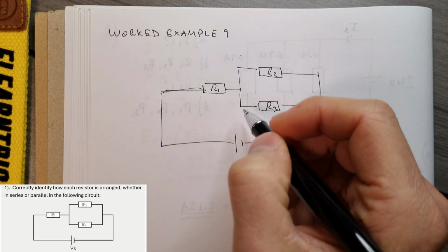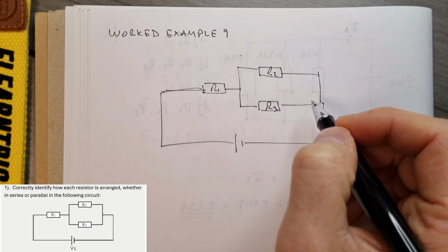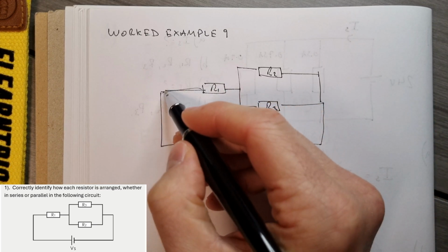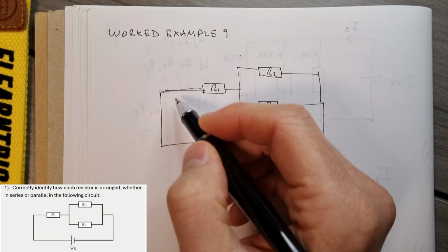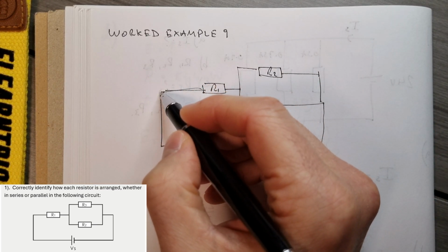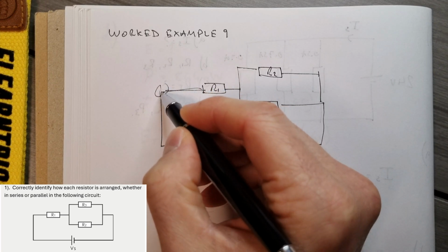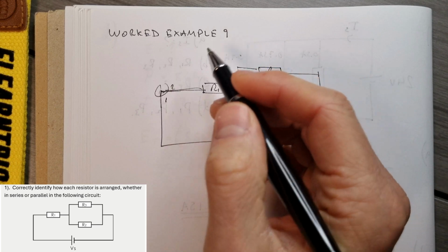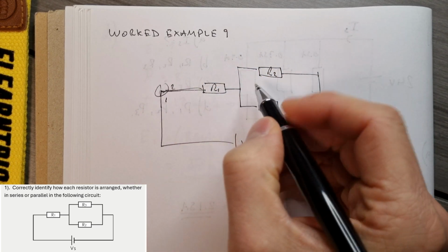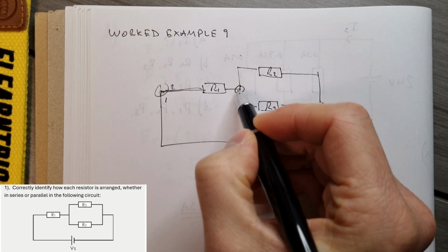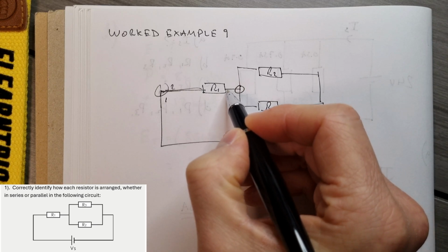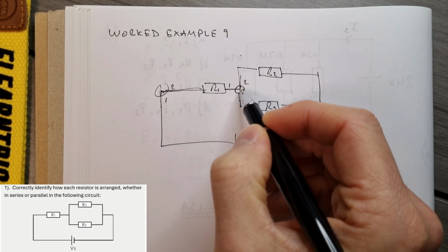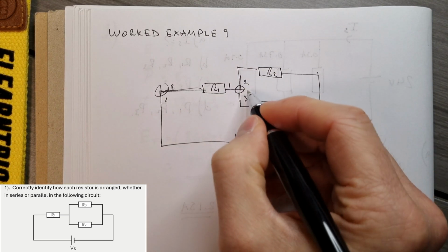First of all, identify all the parts in the circuit where there are effectively 3 or more connections. What I mean by 3 or more is, if you think about a corner, that's not really a connection, but if you wanted to think of it as one, just for an example, you've got a wire coming in, a wire coming out. So that's 1 wire and then 2 wires, so it's not 3 or more. Whereas if we go to a section like this, where the wire is splitting, so 1 wire coming in, another wire coming out, and a 3rd wire coming out, then that's 3 or more,